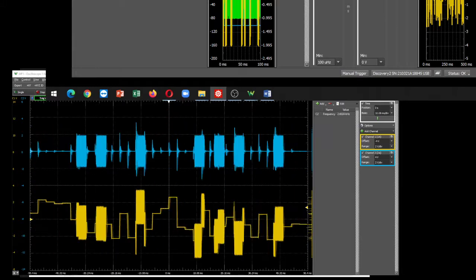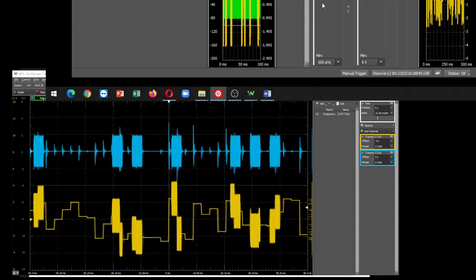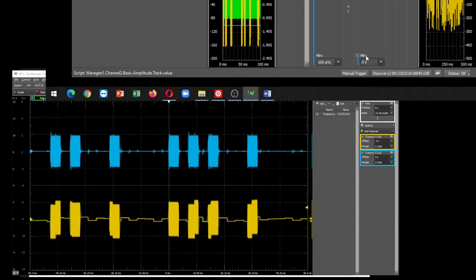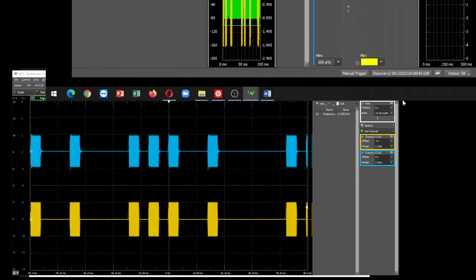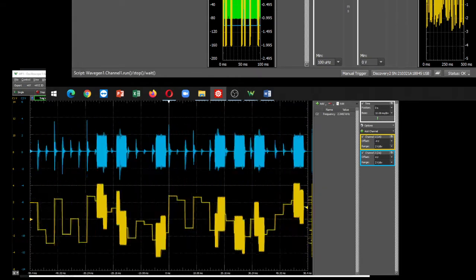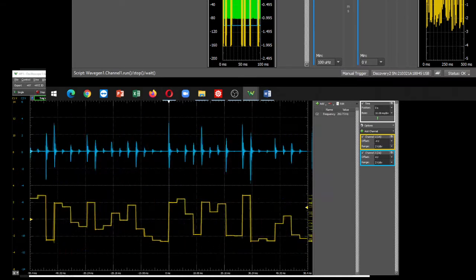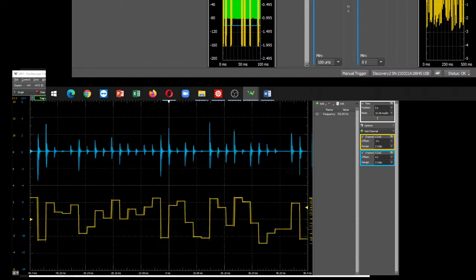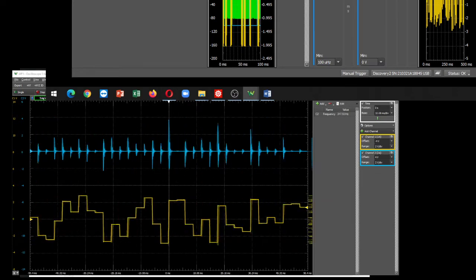Signal alone without noise: largely passed through. Noise alone without signal: only small spike oscillation due to the square step edge nature of the Digilent AD2 simulation. It should be noted that realistic noises statistically do not have such step edges. This type of noise is among the worst case scenarios.